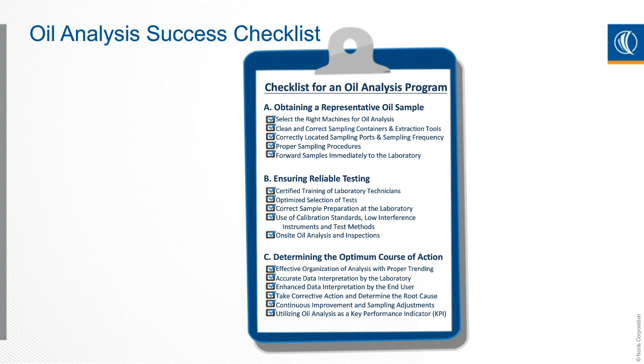All this is about making sure we understand what we are going to do next now that we know what the result is. And also continuous improvement and sampling adjustments, always refining how often we need to take a sample, what we're going to do. And then utilizing oil analysis results as a key performance indicator to tell you the overall success of the reliability of your machines through oil analysis.